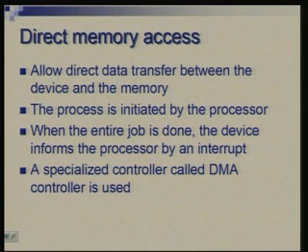Basically, you could say it is an extension or augmentation of the processor logic, which looks after this. The sequential addresses in the memory will be provided by this DMA controller. It will start from the starting address, and as and when data comes, it will keep on updating the memory addresses and detect when the whole transfer is done.